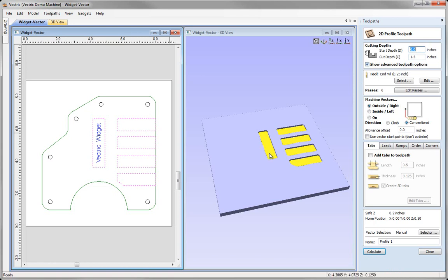In this case, I want to etch this text in the bottom of the pocket we've created here. If you remember, we machined this down to a depth of 1/8 of an inch, and I can see that if I hover my cursor over it at the very bottom of the screen, at the edge of the border of the interface, you can see it's displaying the XYZ coordinates for the cursor. That's down in this area here. Again, if I move that over, it's telling me that that's at negative 1/8 of an inch.